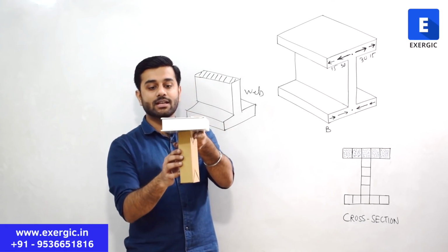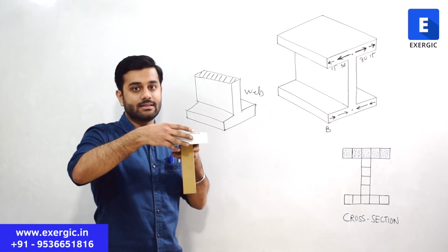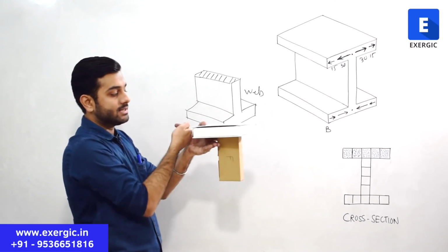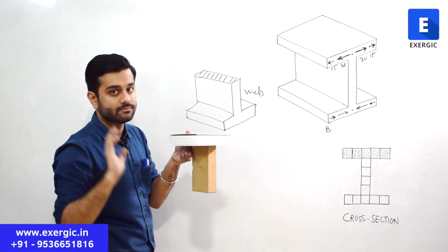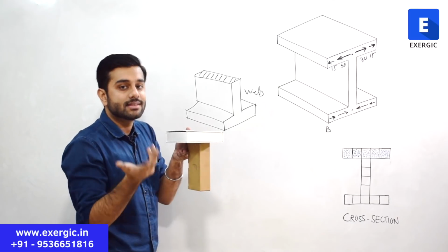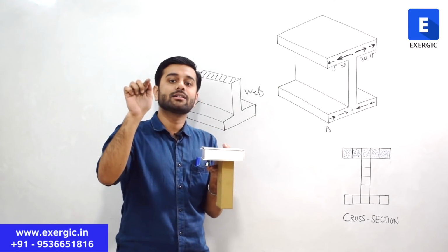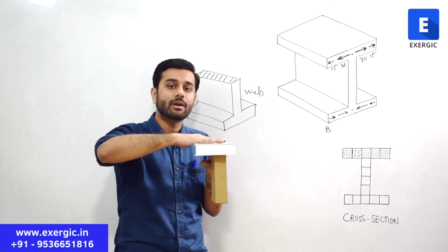So this is the flange, the upper part, and this is the web. This flange is experiencing F1 minus F2 equal to 75. One part of this section needs to resist that. From where can it resist? From that same area through which it is contacting the upper part.